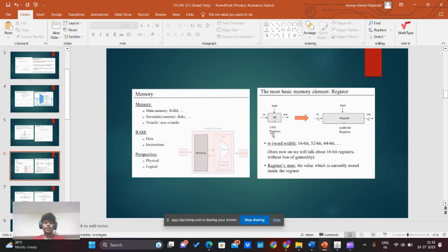The address input determines which register is selected, and the output reflects the state of the selected register. Reading from the RAM device involves setting the desired address and probing the output. Writing to the RAM device requires setting the address, inputting the new value, and asserting the load bit.